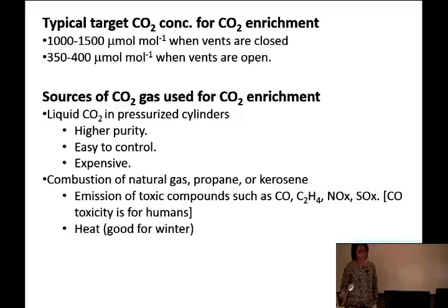When vents are open, you lose a lot of CO2. If you do this, 1,000, 1,500 micromole CO2 injection, growers usually reduce to a level that is still higher than without CO2 enrichment. Remember, when plants are growing and ventilation is going, depending on the ventilation, you can't really achieve the ambient CO2, but you can inject CO2 and achieve that 400 level by CO2 enrichment.